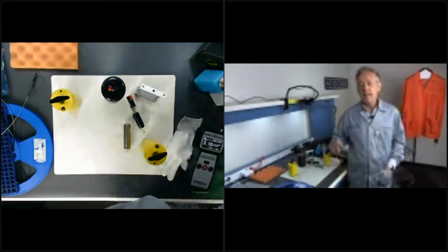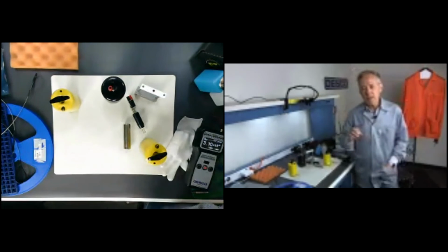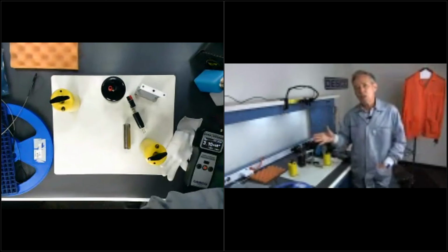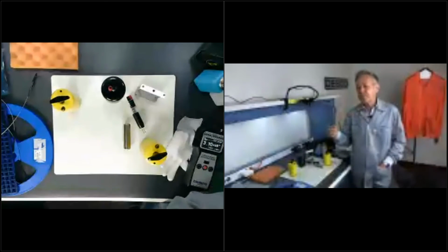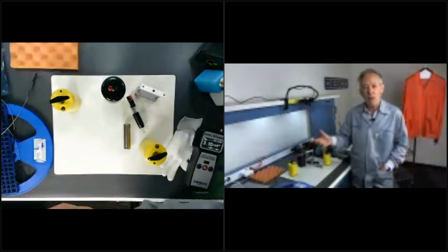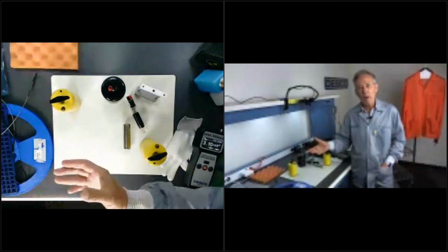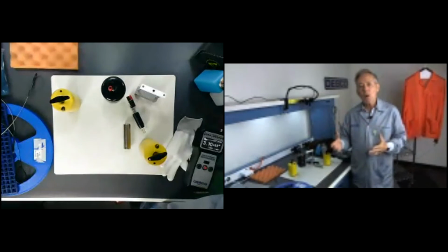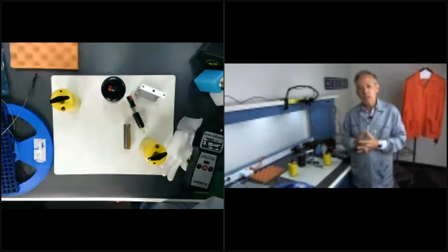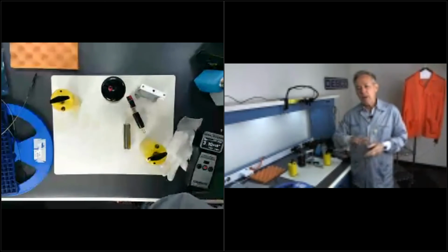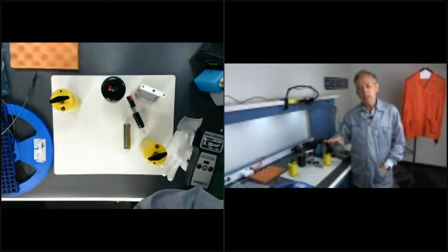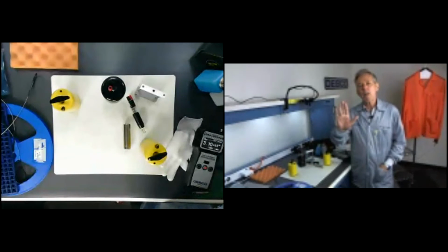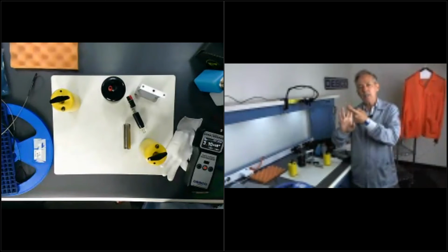Okay, well, that reminds me, I didn't answer the first question completely. This is also in the second question as well. You had asked about a ground rod. How do I check that resistance to ground on my flooring? Oftentimes when a tile floor installer installs an ESD tile, they bury a copper strip in the conductive adhesive, and then they run it up the side of the wall and bond it to the ground of an electrical outlet.